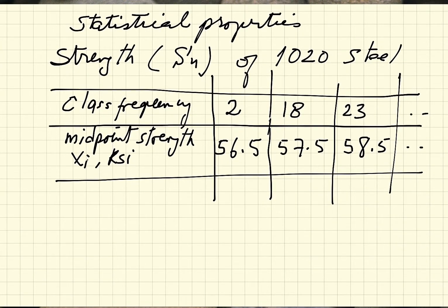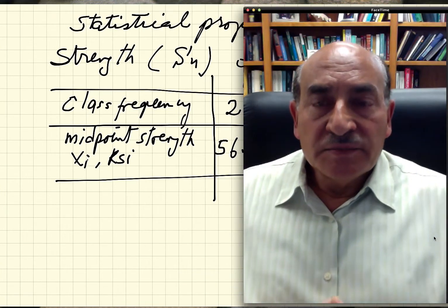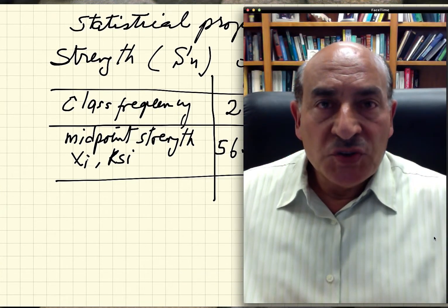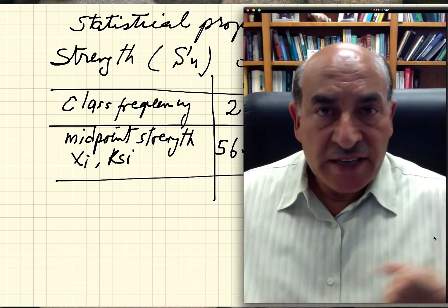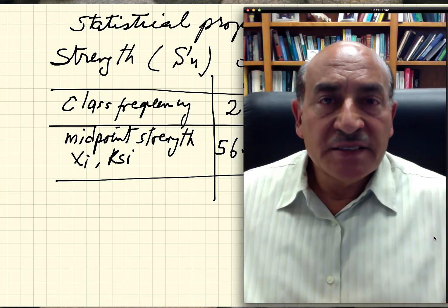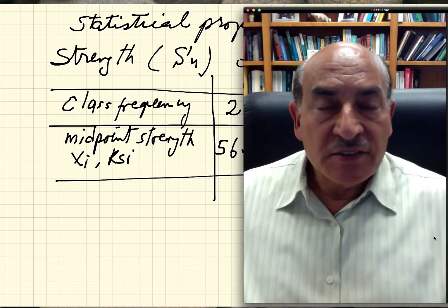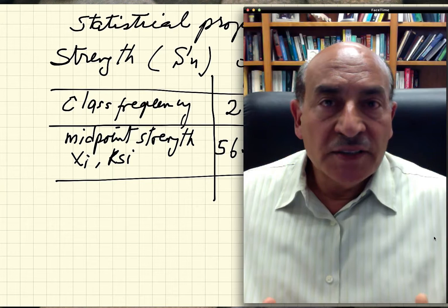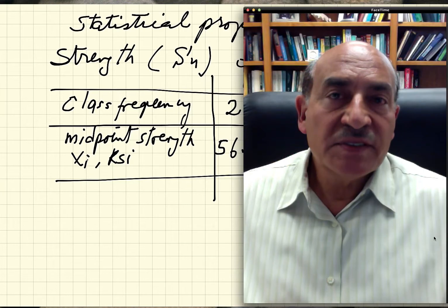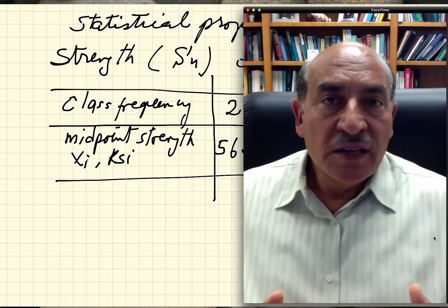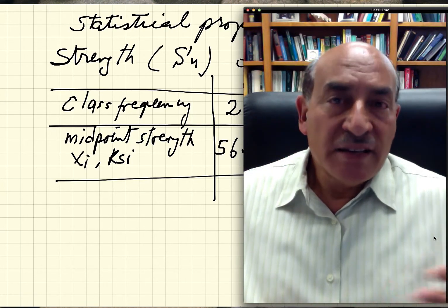That defines the toughness. Let's now discuss what happens if I have a lot from which I chose a sample randomly, and I went to the lab and put it to testing in a machine, tested the stress strain curve, and from that I found the ultimate strength of the material. Obviously depending on the surface finish, the grain size, the cooling parameters, the handling and so forth, I wouldn't expect to get exactly the same yield or ultimate as another sample.